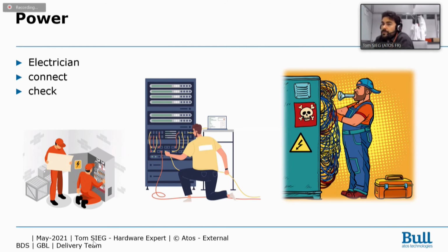Just be careful if your fuse or your protection is activated and your electricity is cut when you plug in the PDU. And of course, after plugging in all the electric parts, you will have to power them on carefully and check that the electricity is okay, going well, and that you didn't burn anything.